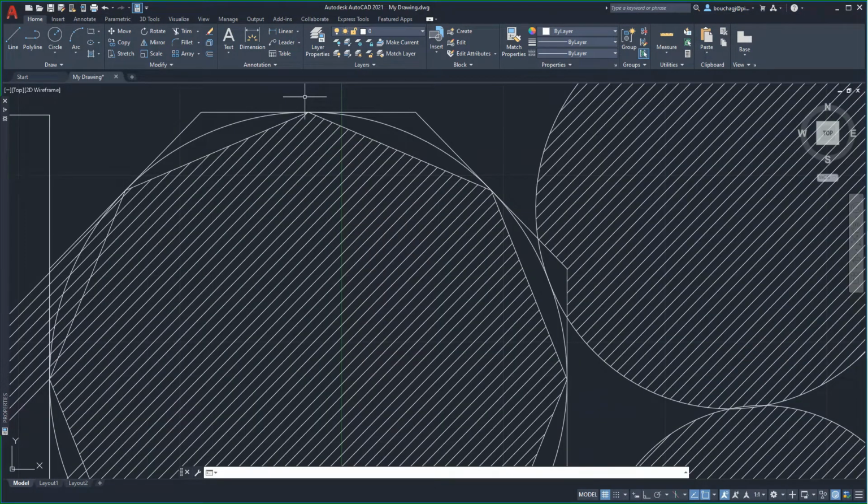Remember the two important points just made. We can deselect objects by holding down the Shift key and selecting the undesired objects, and we should trust the software's detection and recognition of snap points to accurately place objects.